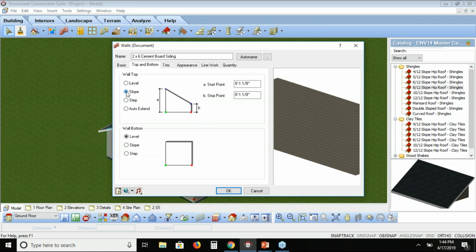And this is how you'd also achieve sloped walls. So think of your stairwell walls. You can automatically slope them to any size as well. You tell them what's the height at one end of the wall, the other end of the wall, and it will slope them. That will change your framing. That will change your drywall counts. You can also step it. So if the wall is going to be stepped underneath those stairs, again, step it. Changes your drywall, changes your framing materials as well.